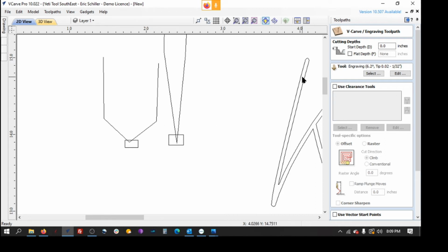And it will vary the depth based on how wide that font is. This font is basically always the same depth until it comes to here. So right here, it would make it deeper so that one edge of the cutter's here and one edge of the cutter's here. Because it's a wider path, it'll go deeper there and then shallow up a little bit.